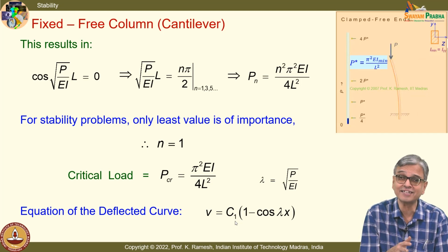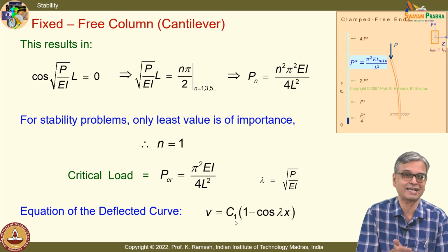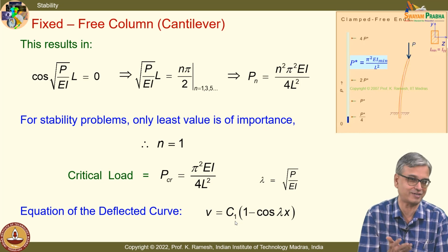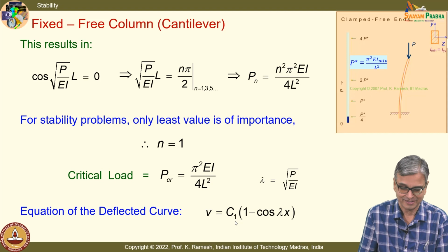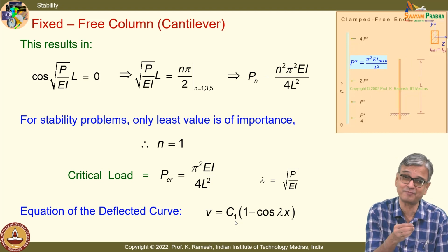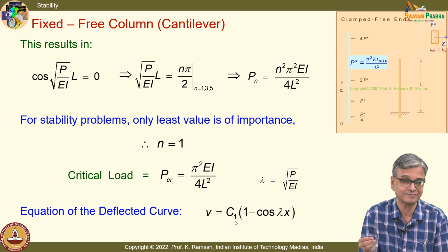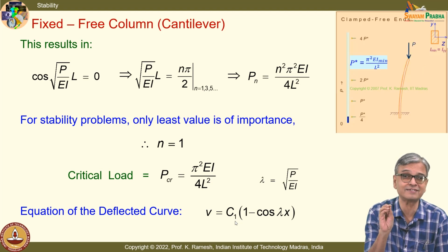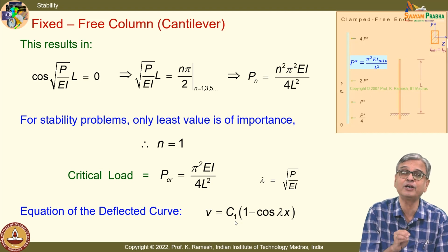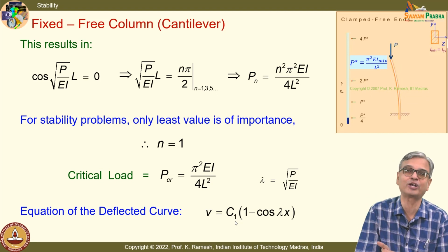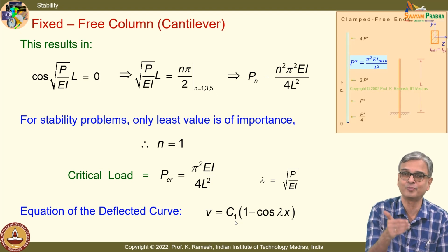You cannot do the analysis, but experiments can reveal it. Experiment does not get limited by your poor ability to solve your differential equation. Fine. That is what we had seen in the experiment. We applied load beyond the critical load, and we saw deflected shapes; they are all neutral equilibrium positions. So, do not mix up the experimental result with your analytical analysis. Analytical analysis stops the moment you find the critical load. Beyond critical load, experiments give you more information for you to ruminate over.